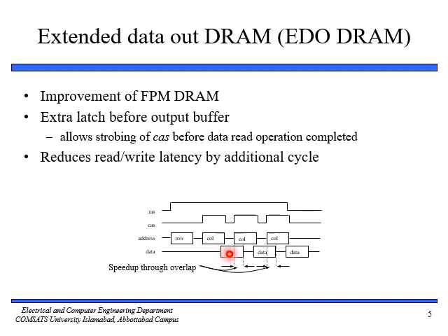But the important thing is that we haven't finished reading the data yet. Our CAS signal starts strobing. Here you can see we haven't finished reading the data, but our CAS signal starts strobing. So we can save this time and read the next column address. Once we are done reading the next column address, we can read and write the data.